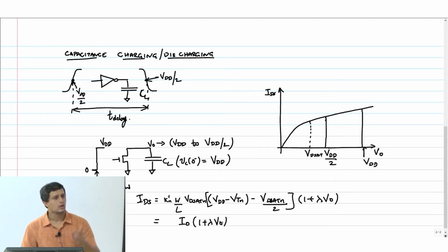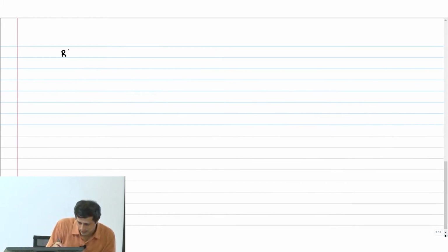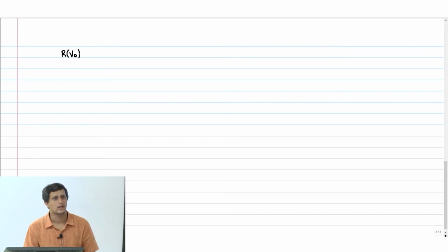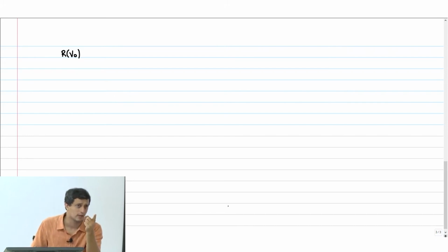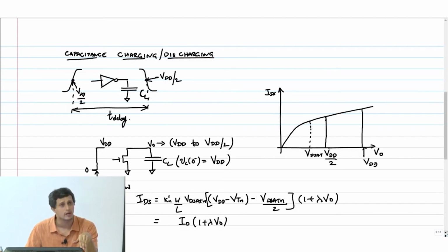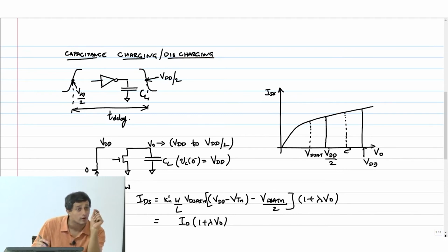Okay. So now just look at the picture. The V naught is coming down. The capacitor is discharging, right? V naught is just the voltage across the capacitor, and the voltage is coming down. So if you look at the resistance, it now becomes a function of V naught. Okay. So last class somebody asked me, why don't you do a derivative out here? See, in analog it's okay to do a derivative because you fix your bias somewhere here, and then you will do some sort of a small signal analysis over that bias point.